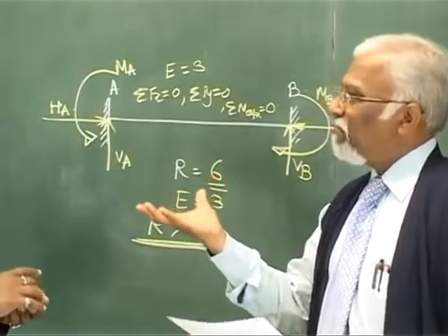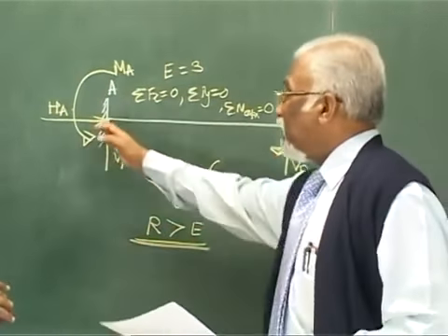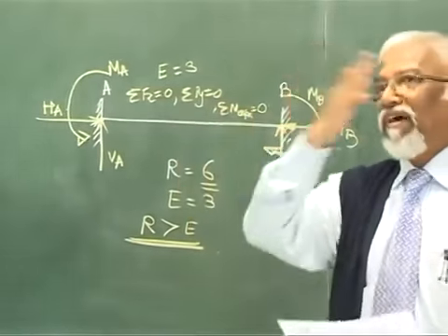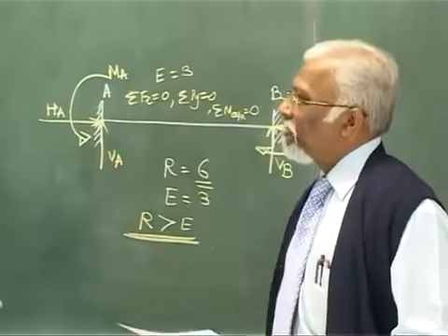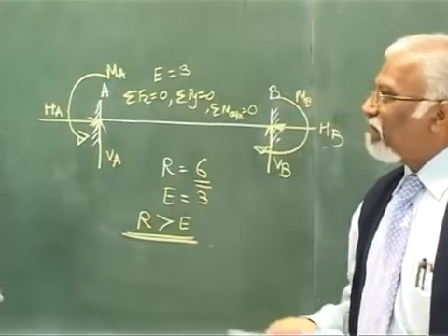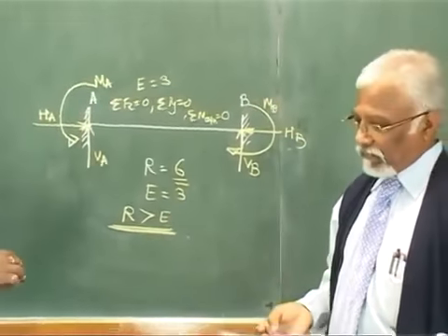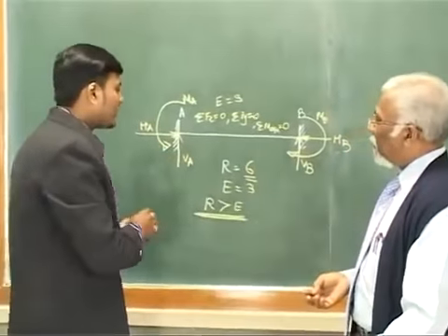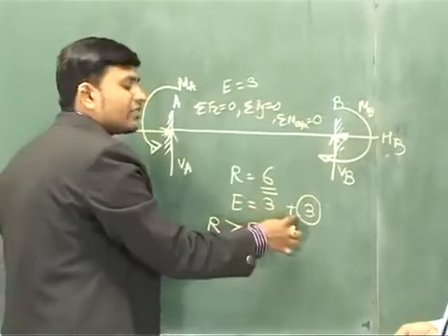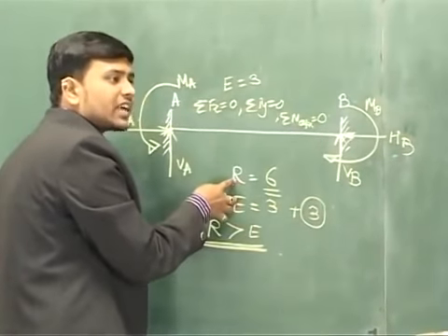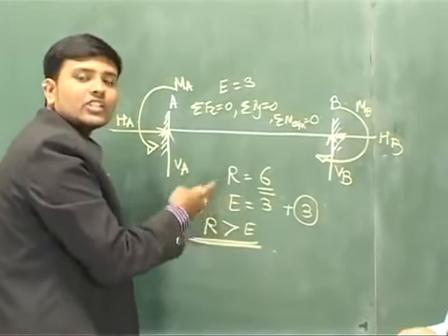Yes, sir. From an engineering mechanics point of view, I would understand, but these types of beams are always there. If I see in a room, they are always fixed. So how would you solve these types of problems? There are various methods by which you can solve such problems. We need 3 additional equations, so that the number of equations will be 6 and the number of reactions will be 6. Therefore you can solve it.